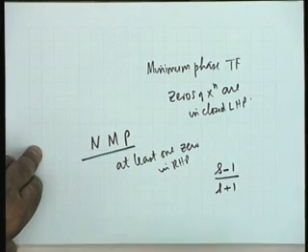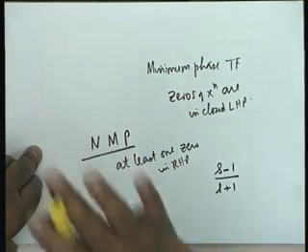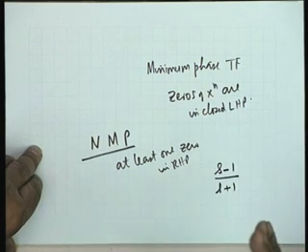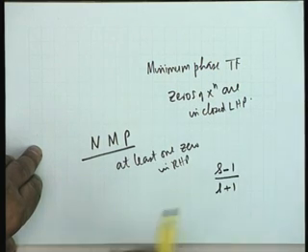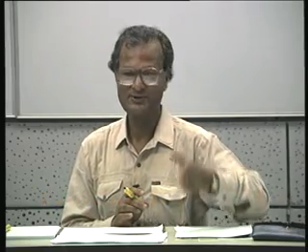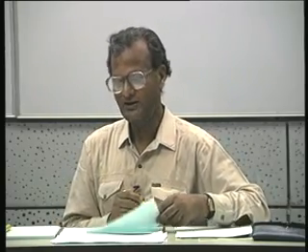In addition, if you recall, all pass functions have the elegant property that, yes, phase shift of course, but the property in terms of poles and zeros, they are not symmetrical. That's not the language. Mirror image symmetry. The symmetry is that of mirror image, considering the j omega axis as a plane mirror, right? The j omega axis is a mirror, there is a mirror image symmetry. So minimum phase and non-minimum phase.